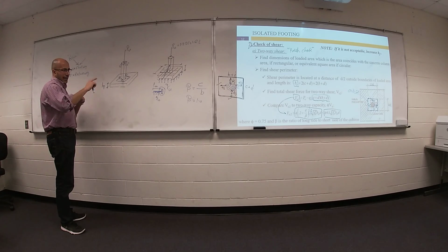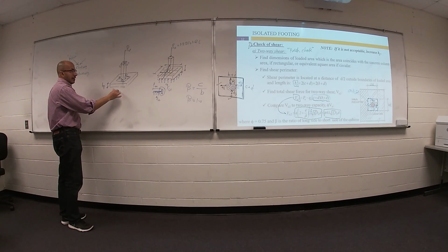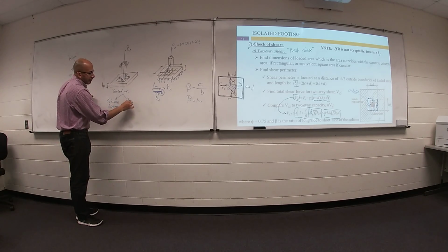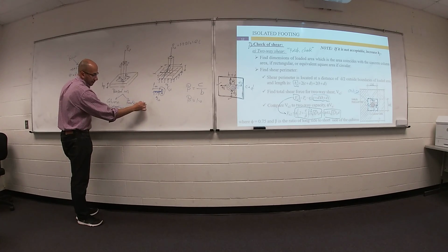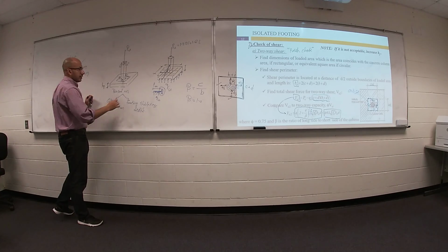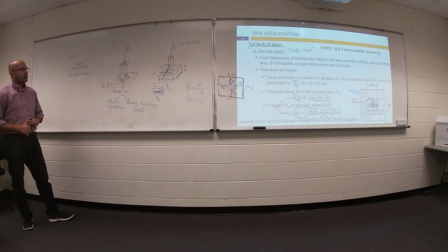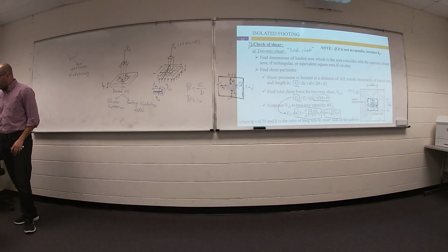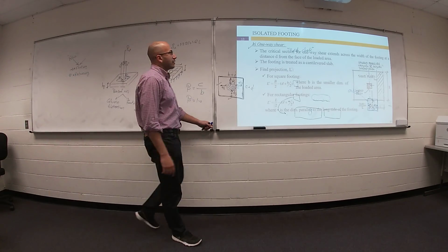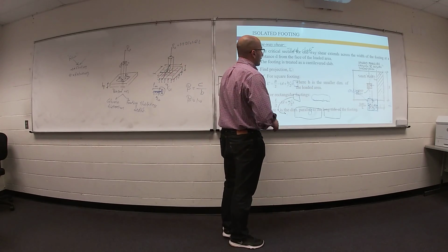All of these calculations are based on two things: column dimension and footing thickness, or footing depth. They are the two main factors to check punch. Once your punch is safe, go ahead and do another check of shear. This time it is called one-way shear, or beam shear.